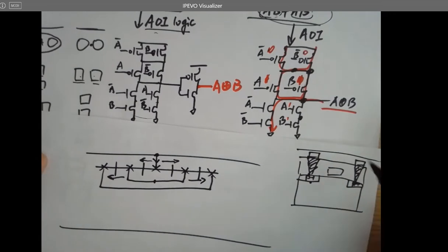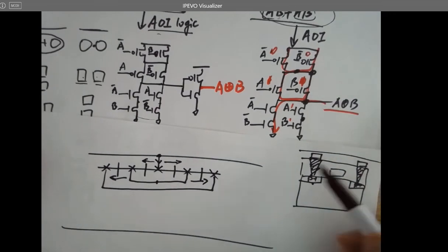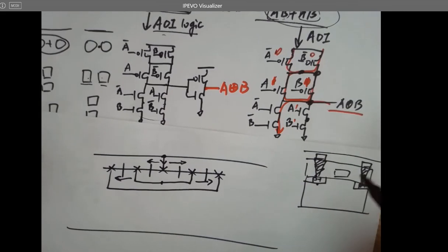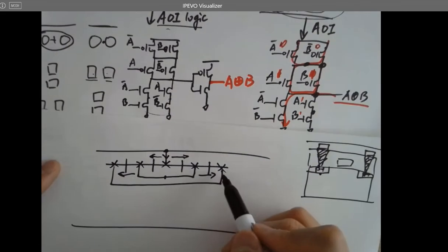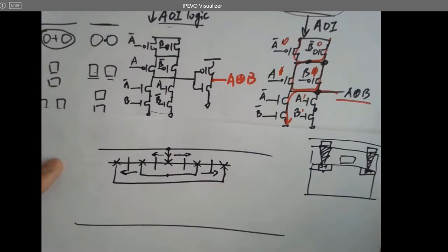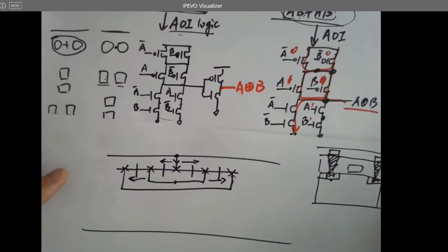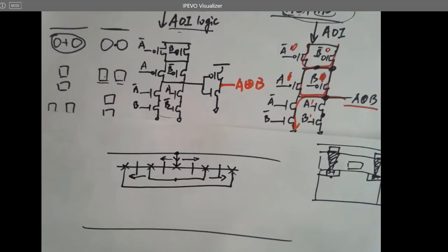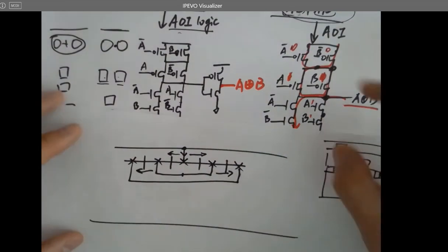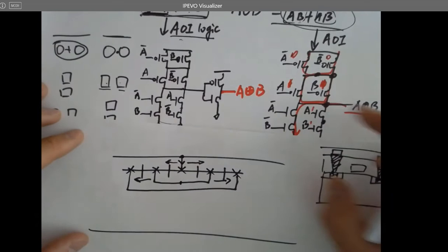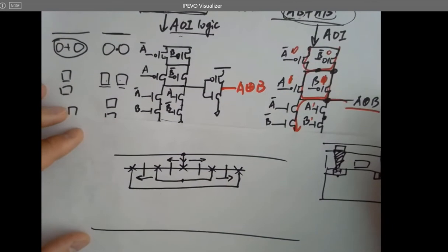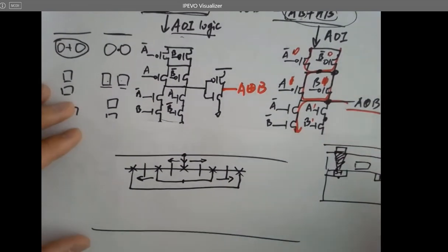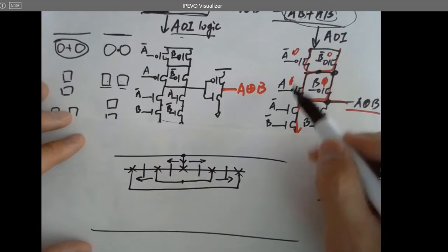And we're going to get into the details of the layers starting from next week. So no worries. So these are metal 1 wires. And after I short these two P pluses together, am I done with the PMOSes on the top? Yeah, done. That's everything for this part of the circuit.